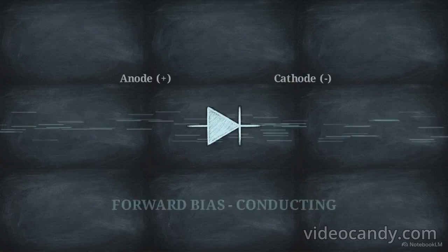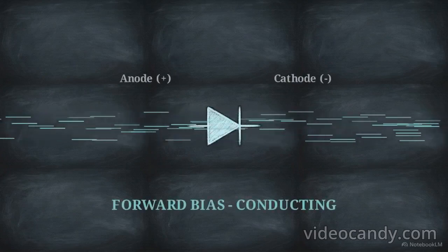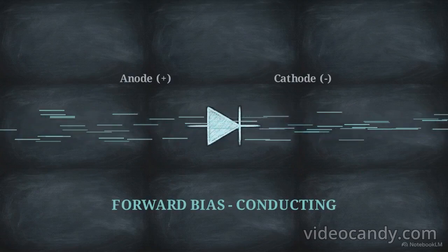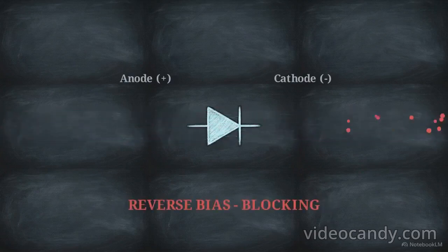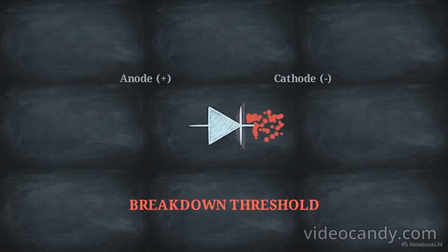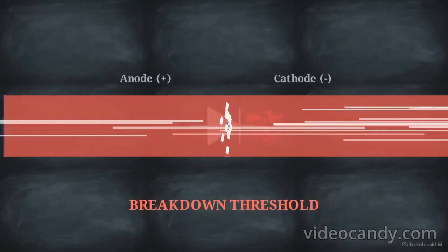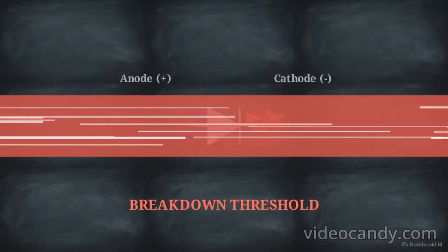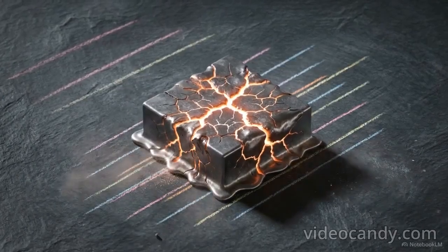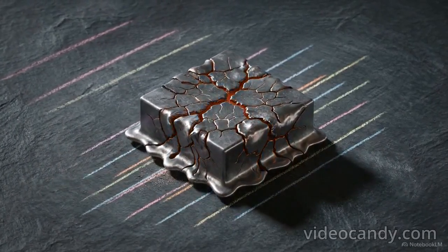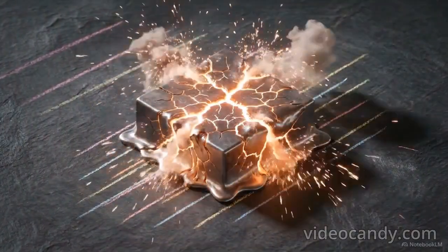A conventional solid-state PN diode serves one primary purpose. It acts as a one-way valve, allowing electrical current to flow easily from anode to cathode while blocking it in reverse. But this blocking capability has a strict limit. If the reverse bias voltage applied across the diode pushes past its specific breakdown threshold, the component fails, allowing a massive surge of current to punch directly through the barrier. Because this avalanche is highly localized, the friction generates intense, immediate heat, permanently melting and blistering the semiconductor material.